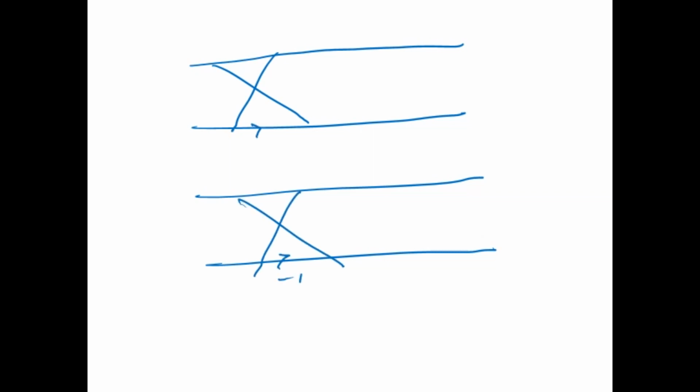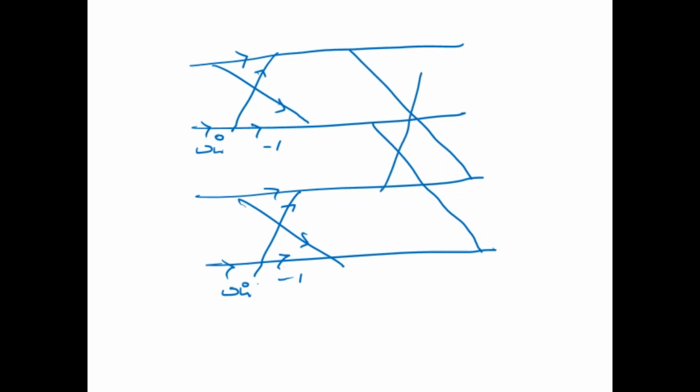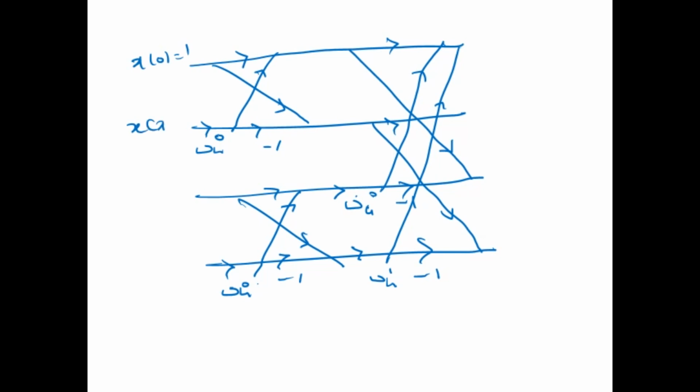So directly we can write, this is 4 point. We have only 2 stages. This first stage, this should be multiplied by omega 4 of 0. This will be the second stage. Minus 1, omega 4 of 0 should be multiplied by omega 4 of 1. So it is given x of 0 is 1, x of 2 is 1, x of 1 is 0, x of 3 is equal to 0.